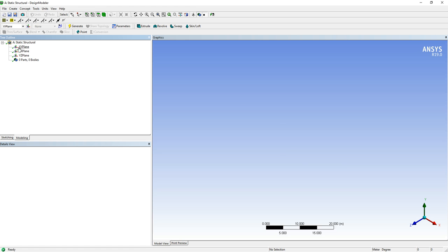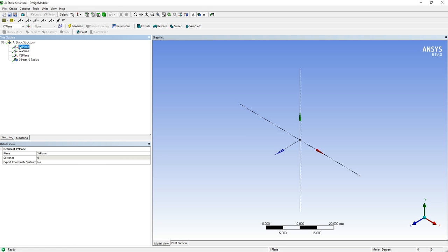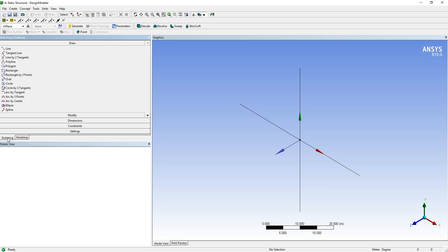So you'll see here on this modeler I can choose plane locations. Here's the typical datum. What I want to do is I'm going to model the bar along what would be the Z-axis. So that is going to be where my extension will lie. So left clicking once onto the XY plane. You see where modeling is? Go to the left, you've got sketching. And I'm going to go circle.